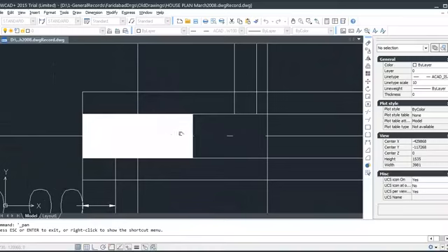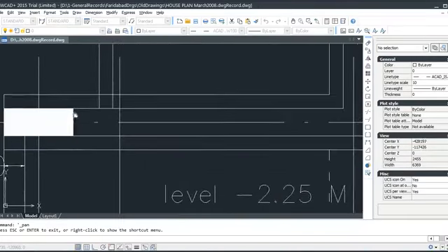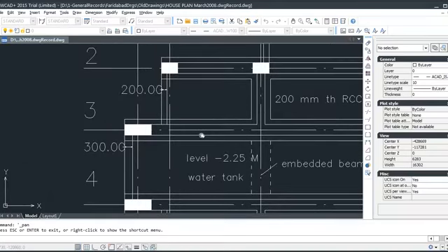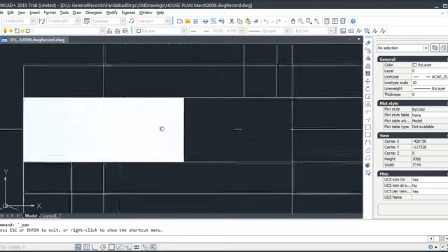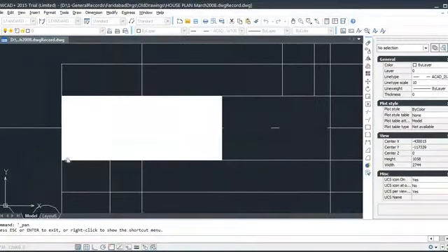Similarly, if I take this, same thing happens to this. All these 4 sides will be exposed to fire immediately, and 3 sides of this slab are also subject to fire, but direct fire impacts these structures. These are beams and columns which are responsible for load and bending moment transfer. So what happens in half an hour, you can say in half an hour, 20 minutes, this portion shall be weakened by thermal impact. There's no major thermal resistance in concrete. It cannot withstand much more temperature. So also steel is there.